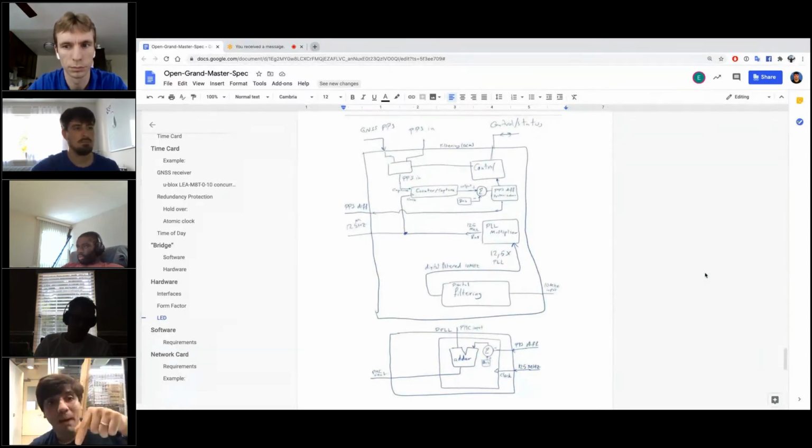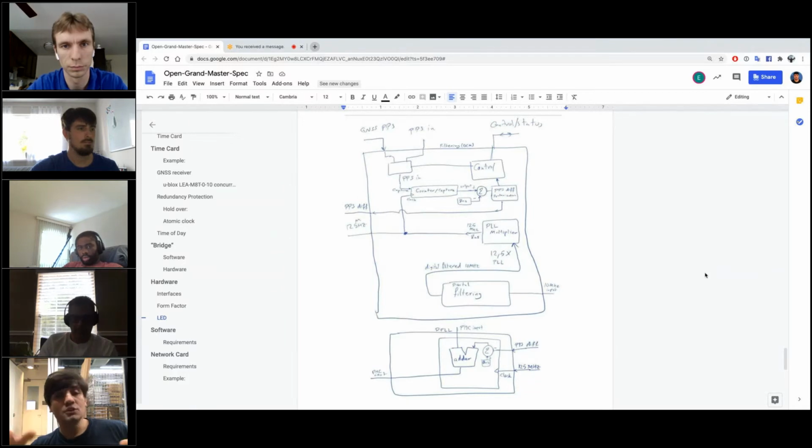You reflect that back because the gPTP timestamp is 80 bits, 48 bits of it is seconds, and 32 bits is subsecond. 32 bits means 250 picoseconds. 8 nanoseconds means you're 5 bits further from the LS bit. So it gives you 5 bits of changes. That's your resolution of adjustments.